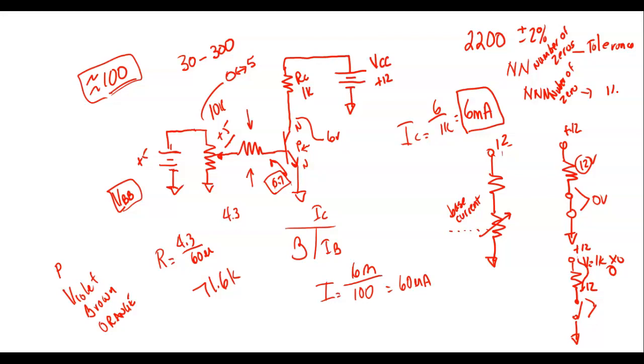I think there's a purple or violet that's available, which is the tolerance for about 0.5%. So it's kind of weird. The red is easy. The brown would be easy. Brown would be 1% in the tolerance band. Red would be 2%, right? But after that, they get real weird. I'll try to get those to you. But these are what we call 5-band resistors. These are really low tolerance resistors, which means they cost more.